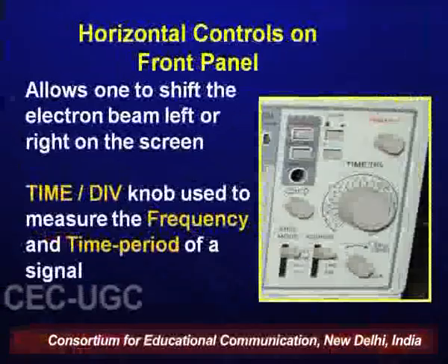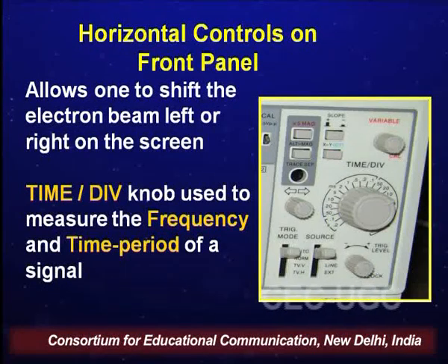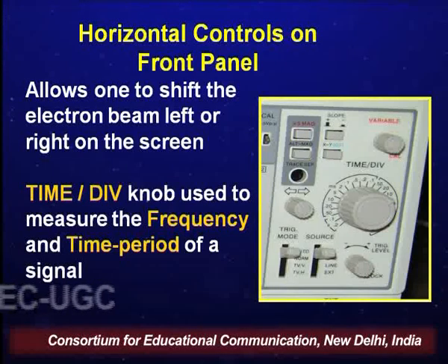So under this X5 mag, if we look at a signal, its time period would actually be 1/5 of what we are seeing. One has to be careful that if this X5 button is depressed, then our waveform is not exactly of the same time period, but rather it is being magnified 5 times.